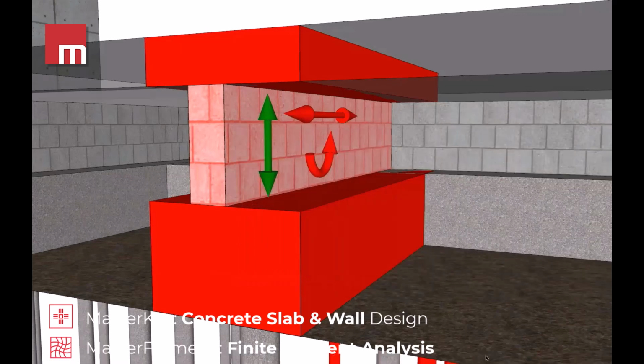Practically speaking, this approach eats into the number of members available in your frame, which could be an issue if you have a member limited version of MasterFrame, for example, and introducing a large number of elements like this can also make the model a bit more difficult to manage.